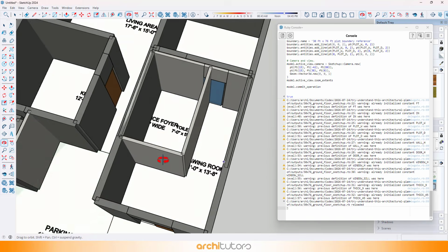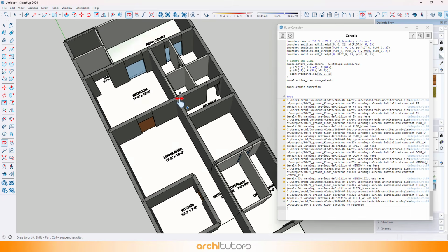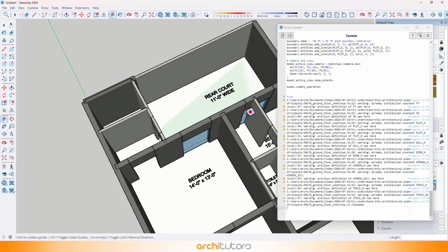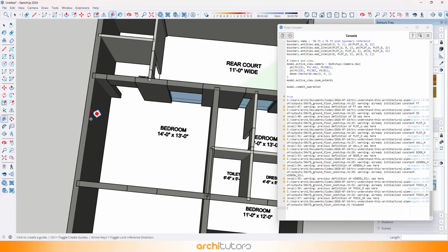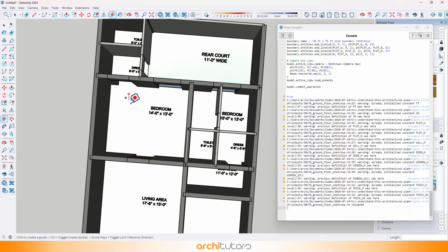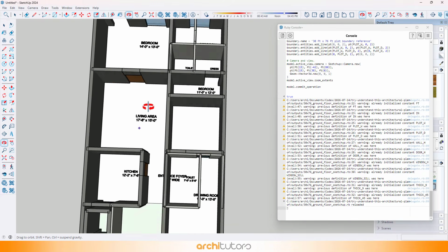Now, let's zoom in closer and inspect the interior wall junctions. You can see that the AI aligned most partition walls right along their center lines. It even picked up the room label text from our CAD layout and converted those into 3D text elements inside the space. Now, to be completely transparent, because no AI workflow is 100% flawless on the first pass, you might spot a few extra partition segments or slight misalignments where a wall corner didn't connect seamlessly. That happens because computer vision interprets overlapping vector lines as distinct structural nodes.